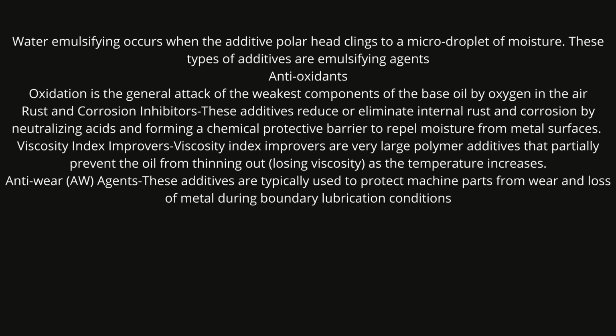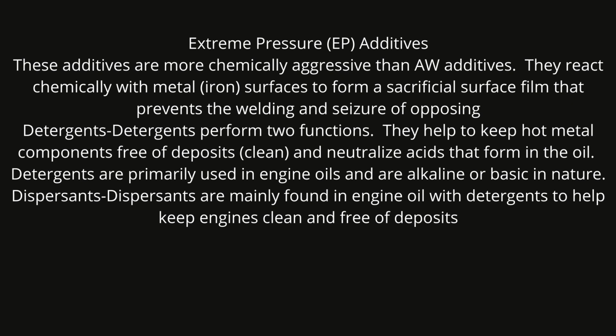Then what are the advantages of adding additives? The details we have given. Suppose viscosity index improver. Viscosity index improvers are very large polymer additives that particularly prevent the oil from thinning out as the temperature is increased. If the temperature is increased, the viscosity property will vary. So that's why viscosity index improver is added in the lubricants. Then extreme pressure additive. These are chemically aggressive agents. Detergents keep components clean.